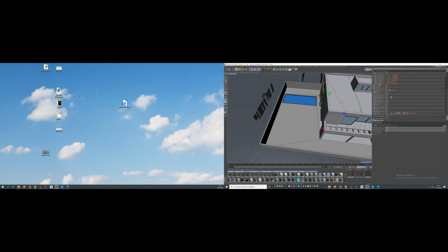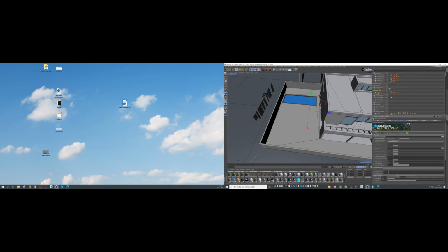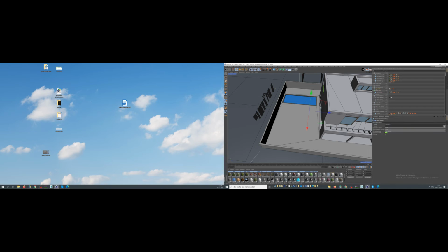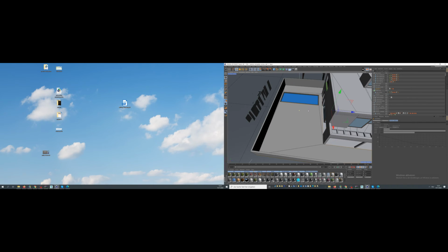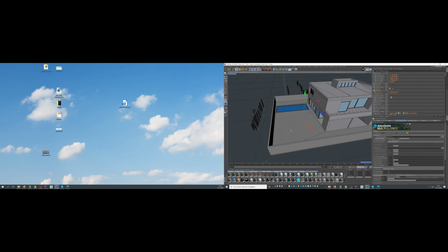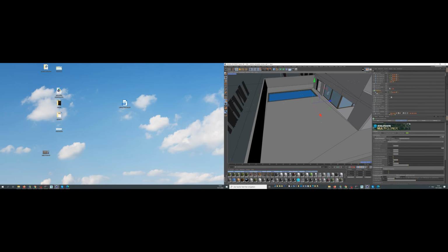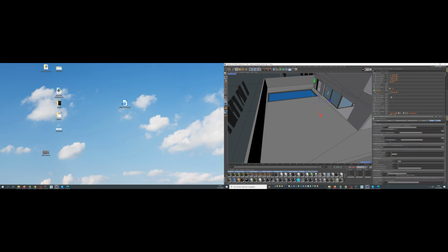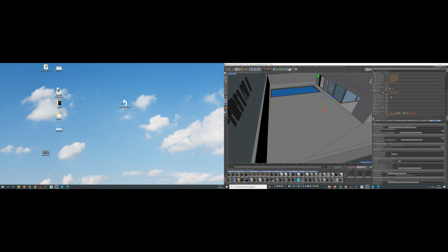I mostly use this one and put it in the multi-cloner. This multi-cloner plugin I connect with the surface distribution geometry. And is it this? Yes, it is the surface. And I add the filtering that I want to use it only on this polygon selection, filter by polygon selection. Now it should be only on this.